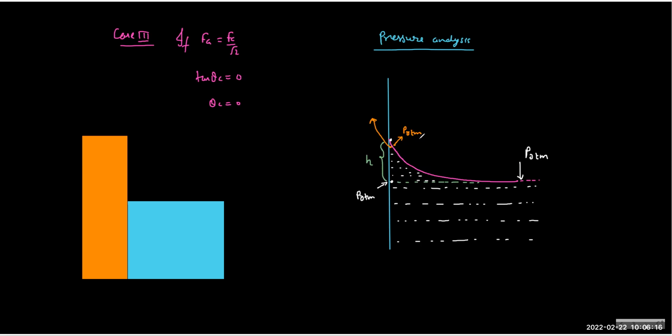So again, with just one difference of side, the pressure will change. On the other side it's PATM, but on the inside we have a pressure. Let's call it P. So what we can write is that P plus rho GH must be PATM if you go vertically down. So you start with pressure P and you go down by H value. So you increase the pressure by rho GH, and so you become equal to the atmospheric pressure.